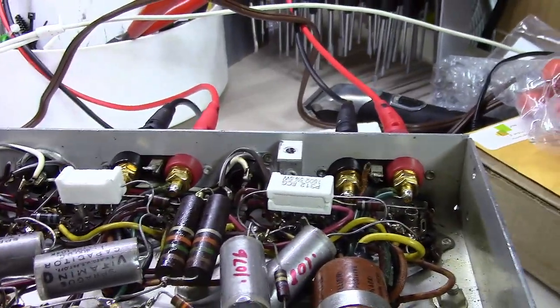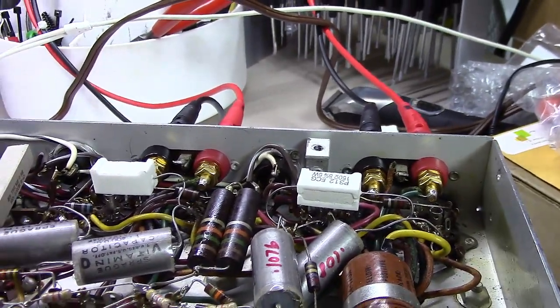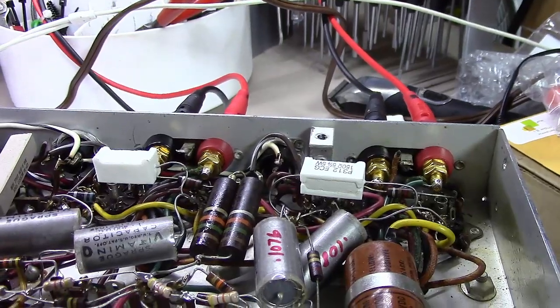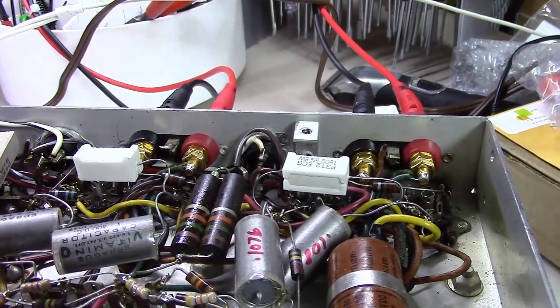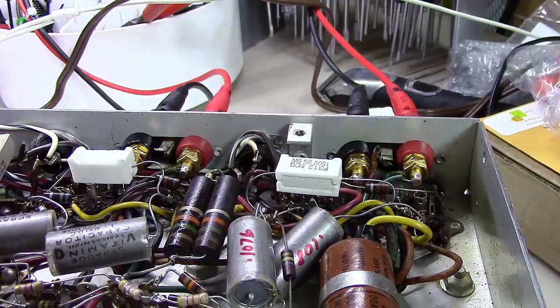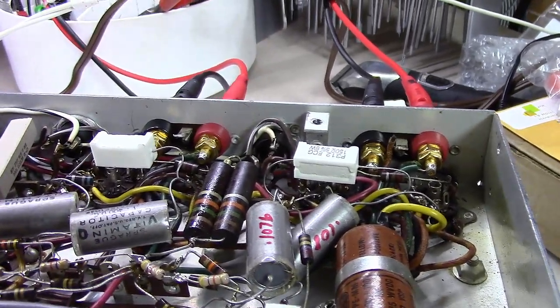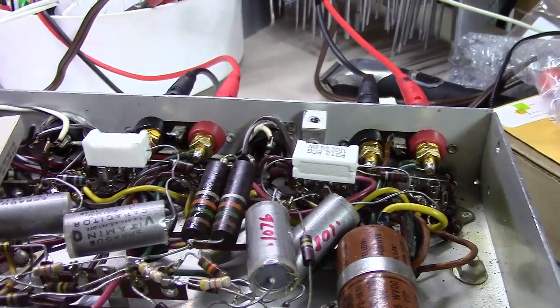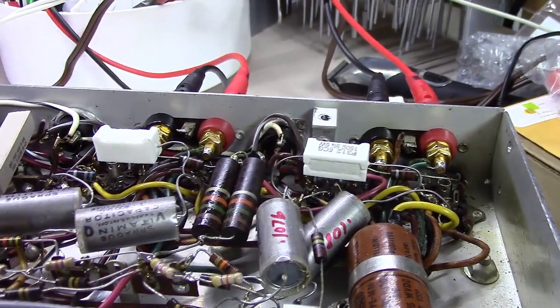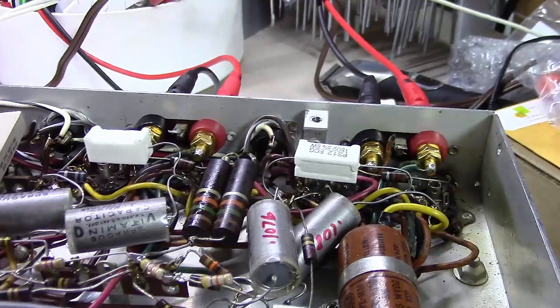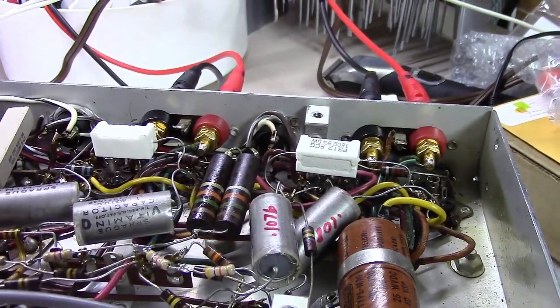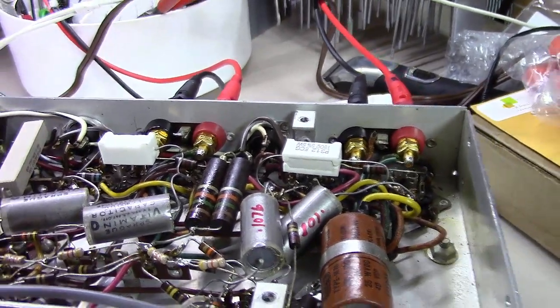That's a very important measurement because as I think I showed you last time, there was a power formula that we used, and power is equal to V squared over R. And so if you took V squared, 8 times 8, right, 64 divided by the resistance, which is 8, you would know then that you were putting out 8 watts of power at that point in time.